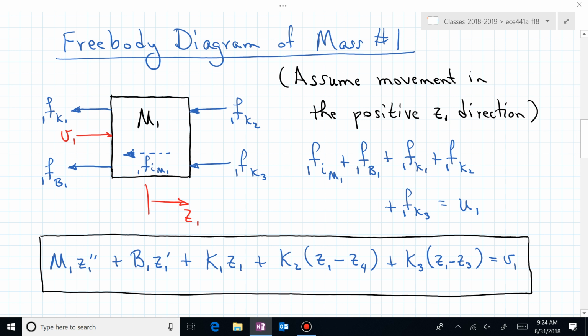And you might just watch the first minute of the Lab 1 video, and you can see the system, and you can see our little cylinder that's a tube, a clear acrylic tube. So you have to be careful, don't drop anything on it. But it now dissipates energy as the mass moves left and right. But it's then proportional. That energy that's removed from the system is proportional to the velocity of that mass.